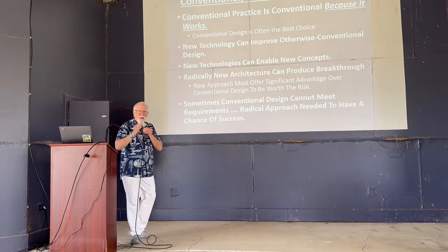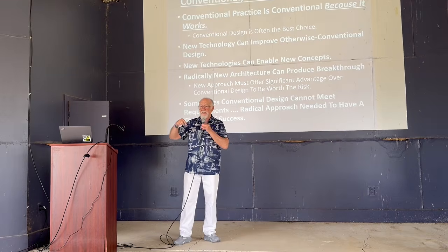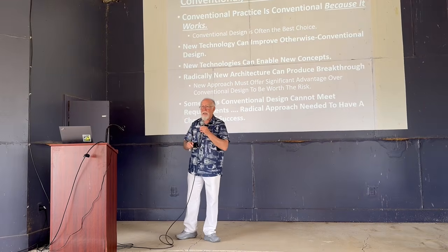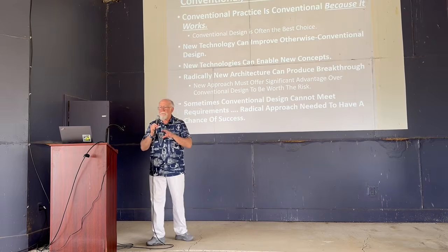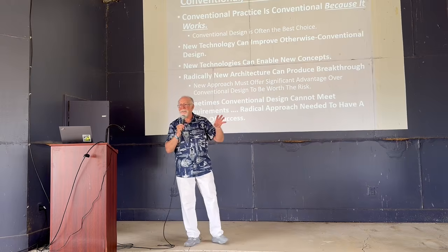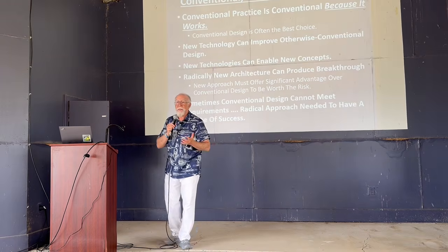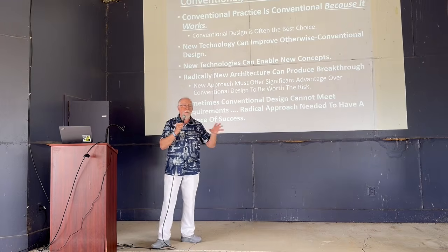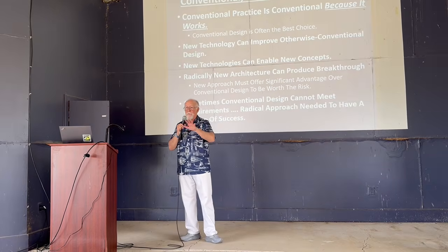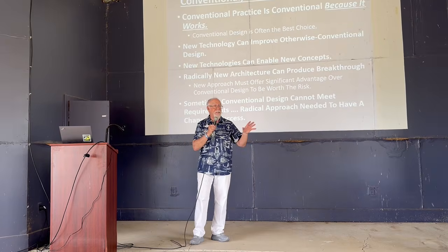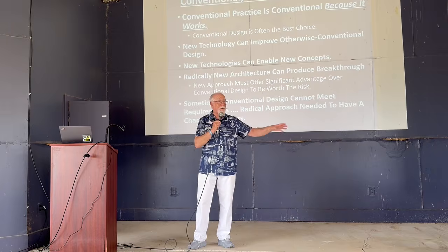Very often, the way a radical design gets adopted is that you can't do the mission the customer needs to do with a conventional design. And sometimes even that will end up with the rehabilitation of a concept that had other advantages but was too risky to try. A beautiful example of that is flying wings. Jack Northrop had the benefits of the flying wing figured out in 1947. If you want to read an absolutely brilliant technical paper, find his 1947 Wilbur Wright lecture about all-wing airplanes. Everything he said about range payload performance was 100% correct.